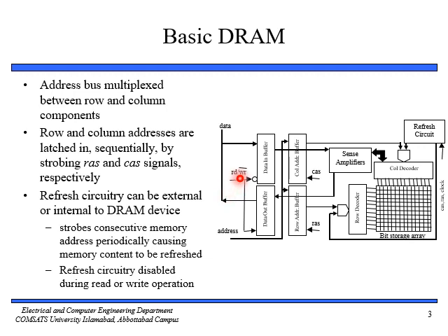For read we are just going to data out, whereas for writing we have the write bar, so data in. Data in goes towards the sense amplifier, whereas for reading, the data comes out of the sense amplifier. And here we are going to access the column and here we are going to access the row.